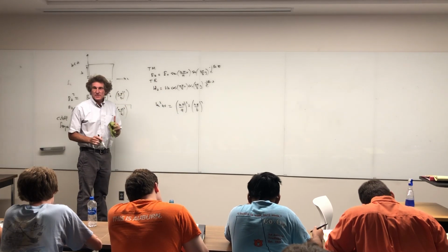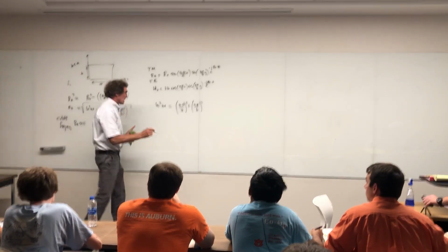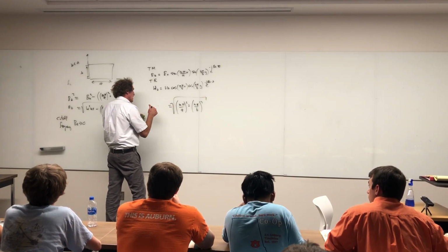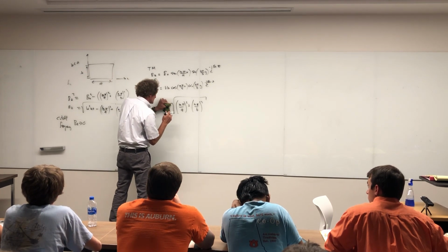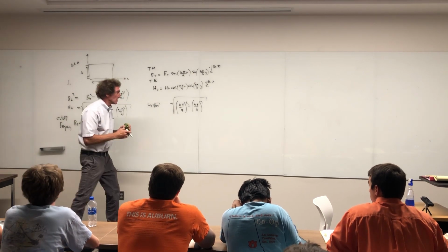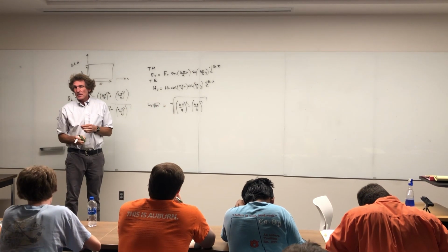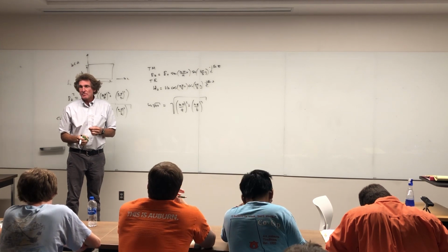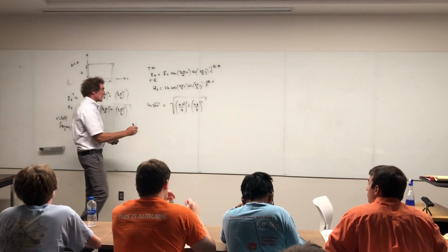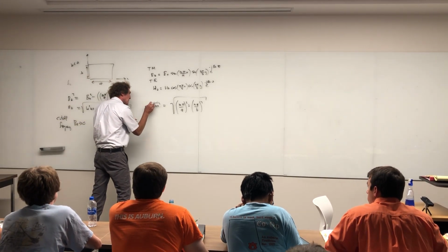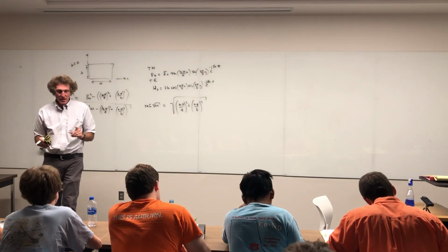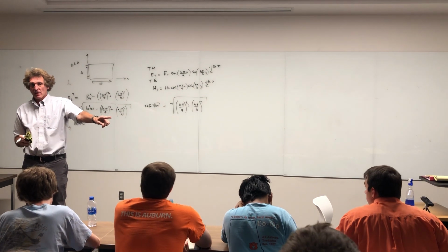I'm going to take the square root of both sides, okay? So I take the square root here, and that means this becomes omega c times square root of mu epsilon. Do you all agree with me here? Right? Keep watching. Now what is omega c? Omega c is 2 pi fc, isn't it? So I can say this is really going to be 2 pi fc. Follow me? That's what I want, the cutoff frequency. That's what he asked about. With me on this, class?